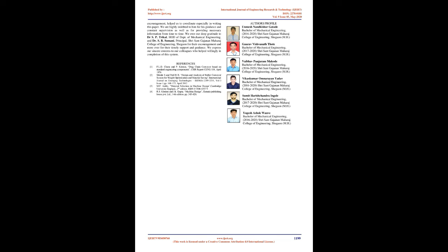4. Result and discussion. The required modifications achieved in this project are: A. The fatigue cycle damage is reduced from 13% to 3%, followed by fatigue analysis on the shaft. B. As the drive shaft assembly was initially overweight, we successfully reduced the weight by using FRP material and optimized weight is achieved.